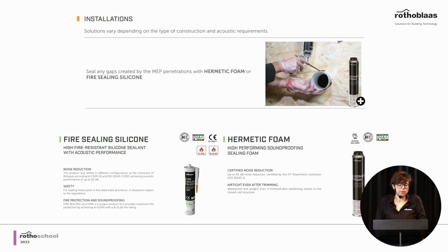And we have already said that many times. So when some part of the installation affects the air-tightness, it's very important to restore the air-tightness with sealant, silicones, foams, and so on. Pay attention that this material needs to be tested and approved from an acoustic point of view. So not all foams are suitable for this purpose, not all materials are suitable for this purpose.